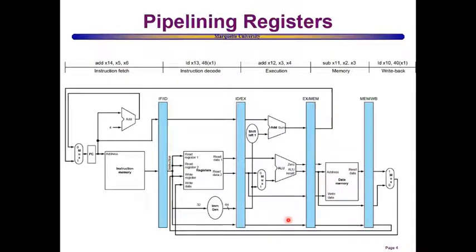The first pipeline stage gets its output latched in this pipeline register, instruction fetch / instruction decode, that will provide that information at its output as input into the second pipeline stage, whose outputs will be latched by the second pipeline register, instruction decode / instruction execute, that will provide that information as input into the third pipeline stage, and so on, clock cycle after clock cycle.